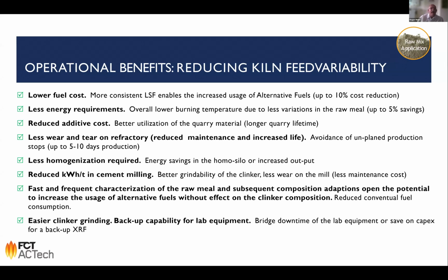So using this analyzer can result in different benefits. By having a more, let's say, constant and consistent input into the kiln, you have a standard deviation of the LSF which is much lower. And this will result, on the one hand, in lower fuel cost, because if you have a very good track on the LSF, you can also optimize the use of alternative fuels. And this can lead to a significant cost reduction in the process.